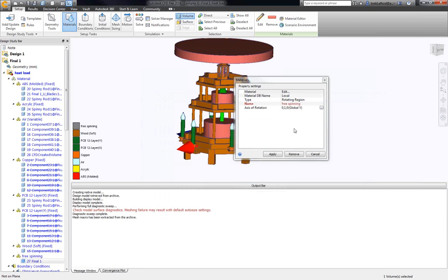So I guess earlier when I said there weren't any, yes, there are, just as long as you're aware of the inertial mass when you do suppress. Right. Okay. And again, that's going to come across as an assumption, and as long as it's an even assumption behind all of them, that's another one that I actually did here. I just picked an inertial mass versus really calculating it. I knew I wanted it to have a reasonable amount of resistance. It probably should be higher, but as long as it's the same between my designs, I get to know which was the better design.